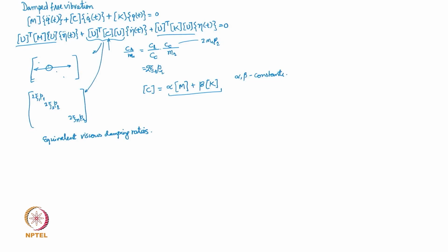Now this is definitely not going to represent the actual damping in the system. However, it has also been discussed and highlighted that the actual damping in the system is very complex, and the damping parameters are not so easy to get. So when you cannot quantify the damping properly in terms of its value as well as its form, for the sake of getting reasonable vibratory solutions, these are the ways of getting around this problem.